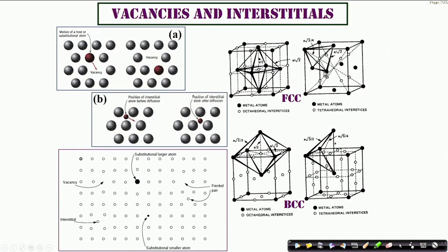And since this is geometric, where we can calculate exactly the length of these arms, we should also be able to calculate exactly the diameter of these vacant sites. So the size and location of such interstitial positions can be geometrically determined using such considerations, both for FCC, BCC, and for that matter any other kind of Bravais lattice.